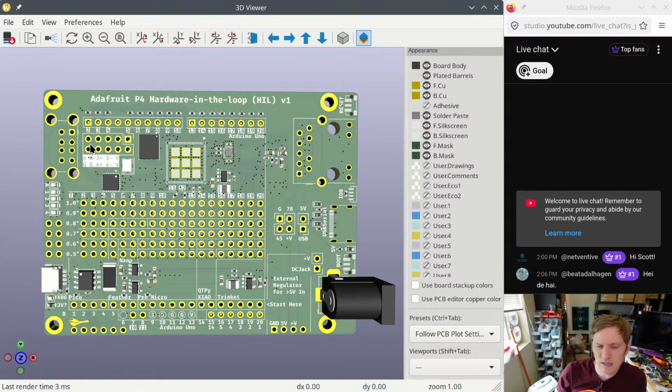I was just tweaking all of the silkscreen. I do silkscreen kind of last, because you want to avoid components. For example, here, the 11 and 12 are above where these resistors are. I can't put the resistors closer because there are traces being fanned out, but you can put silkscreen over traces just fine.